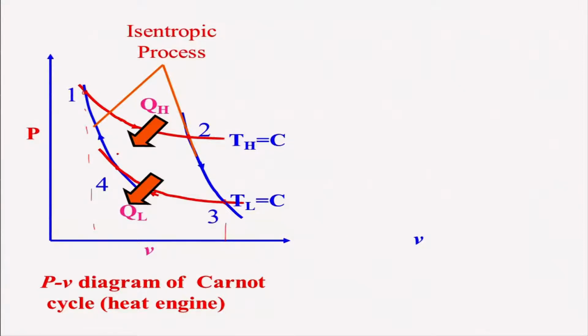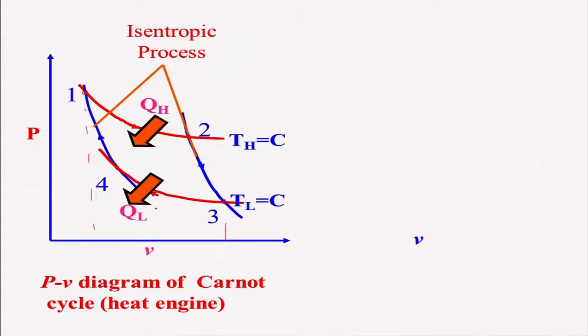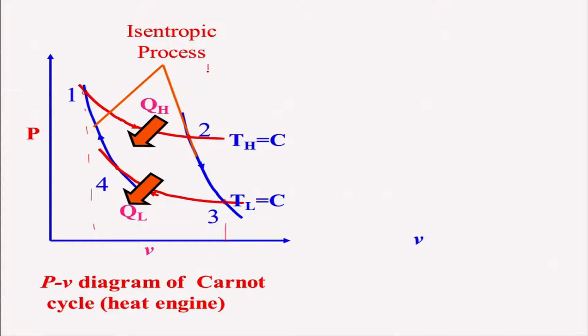and after this there will be isentropic compression taking place again from state 4 to state 1. So, if you look at, heat is given, some work input will be given by the surrounding to the system, because work is done on the system, not by the system, on the system. So, this is the amount of work which you need to supply, that is 1, 4 and 3. This amount of work you will have to supply, and 1, 2 and 3 this work is being produced by the engine. So, therefore, what will be the net work done here? Net work done, we know that net work done will be QH minus QL. Am I right? Because heat is coming in and then is being rejected, and that is the work done.